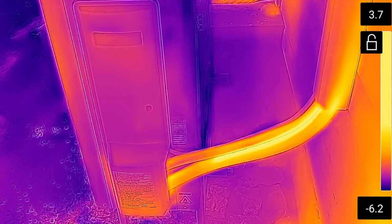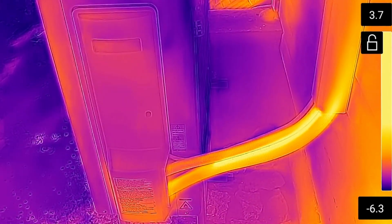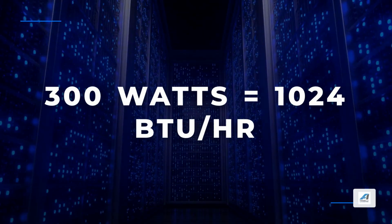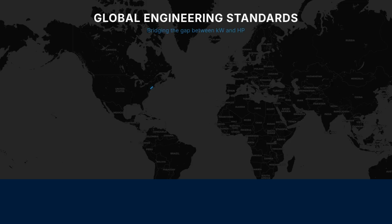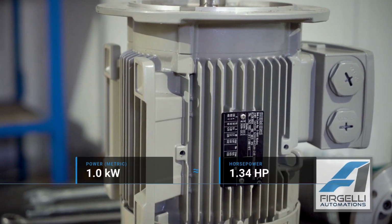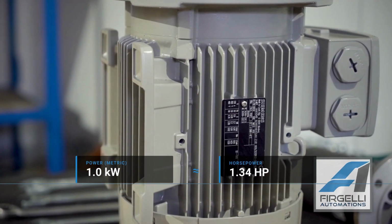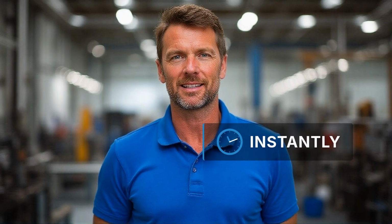Second, thermal management. HVAC engineers and enclosure designers work in BTU per hour. If your system dissipates 300 watts of heat, that's about 1,024 BTU per hour, and this converter gives you that number instantly. Third, international projects. You're sourcing equipment from Europe rated in kilowatts, while your documentation requires mechanical horsepower. Instead of hunting through reference tables, you type once and read every unit at a glance.